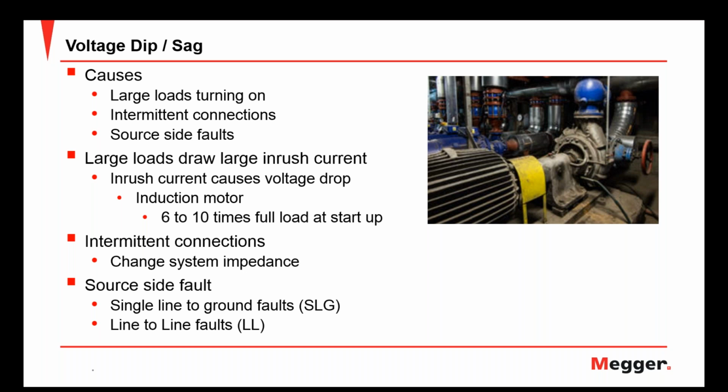When they're source side, for the most part, when the voltage goes down, you'll see the current go down most of the time. If you have a motor load, you could see the current go up, but for the most part, that's a good methodology to help determine if it's source or load side, but you do need to know what your load is.